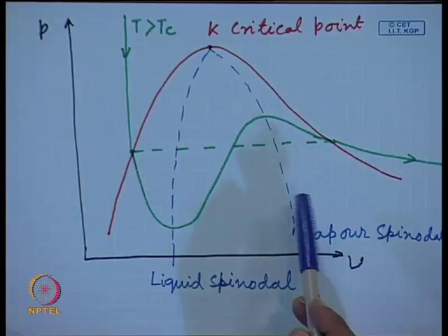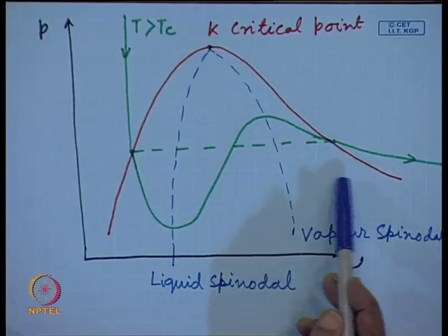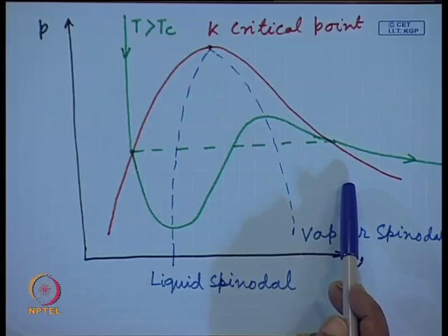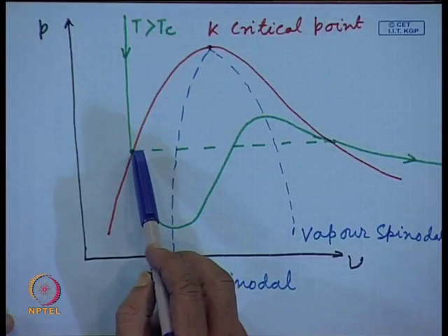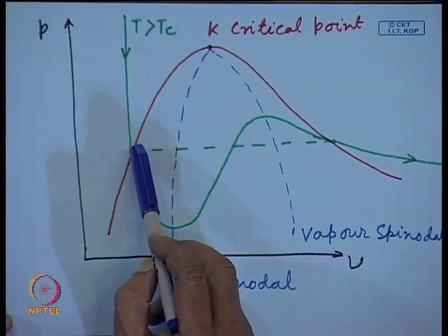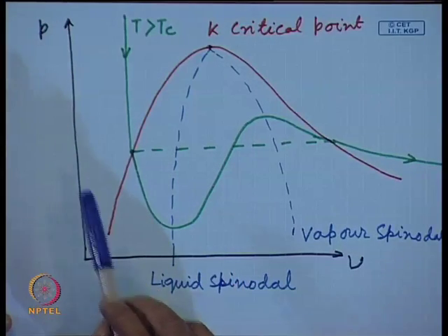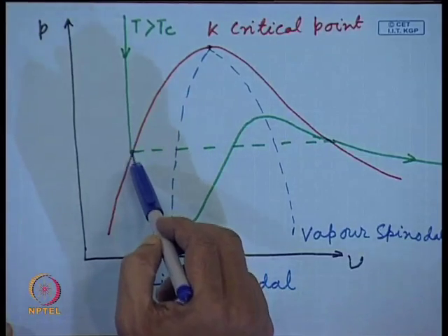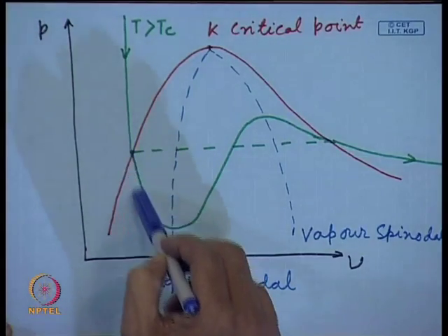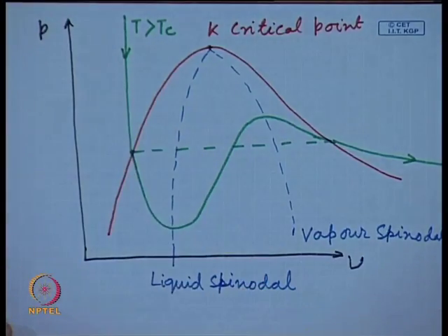On the other hand, on the right hand side of the curve, we will have a metastable vapor state. So, it will try to remain in the liquid state only, though the temperature here is the saturation temperature corresponding to the pressure. Now, what we can see is the temperature is remaining constant and pressure is reducing along this curve up to the liquid spinodal.